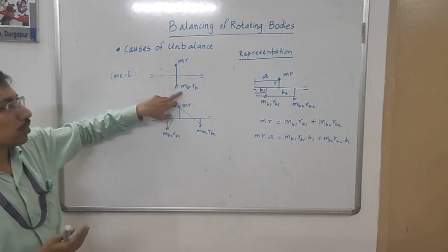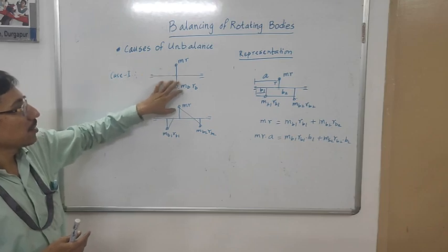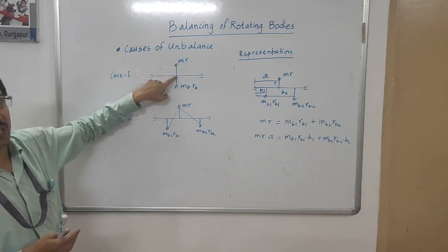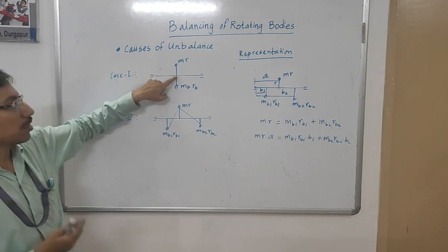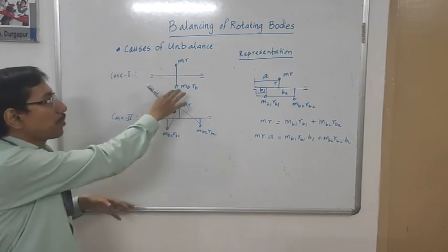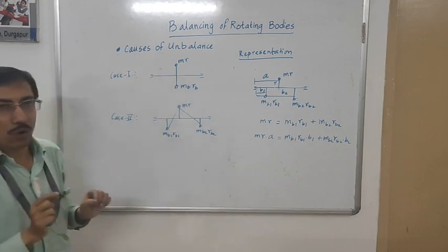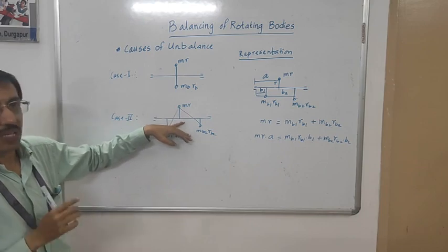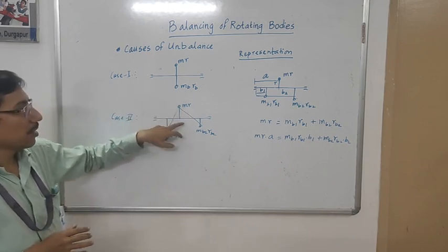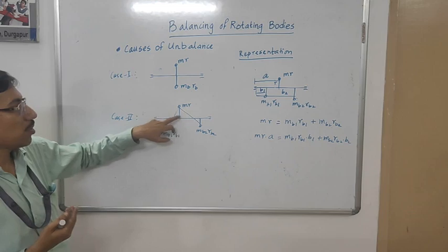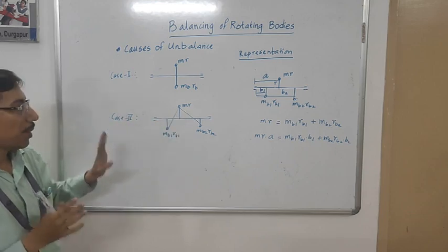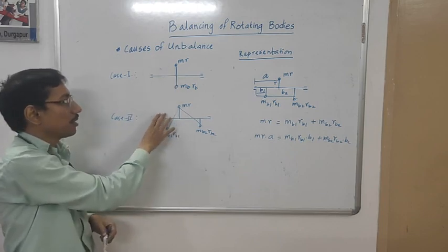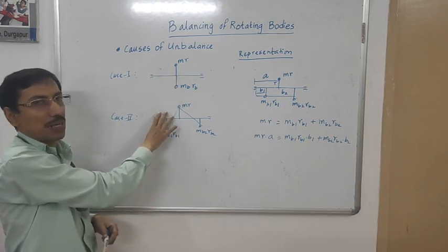this, what we did actually, the resultant center of gravity of this whole system now lies on the axis of rotation here. So the center of gravity of the whole system, after putting this balance mass, is now on the axis of rotation. So here also the same thing happens. That is, the resultant center of gravity would lie on the axis of rotation somewhere, but the difference is it is externally balanced but internally unbalanced.